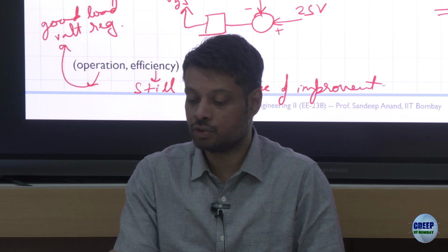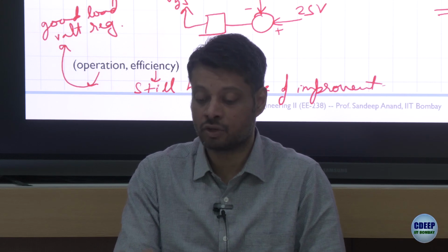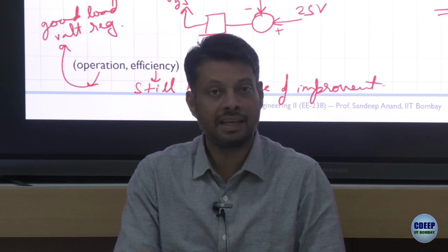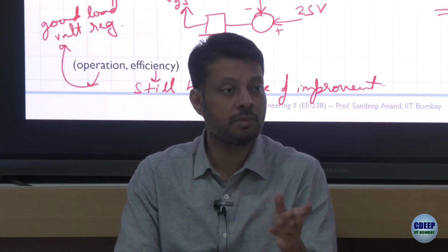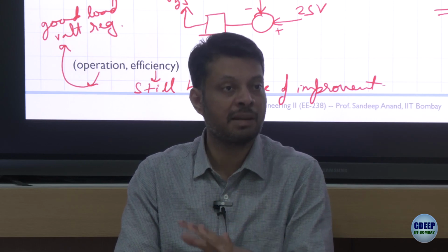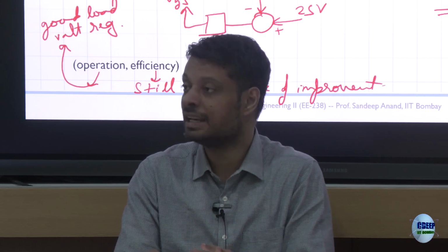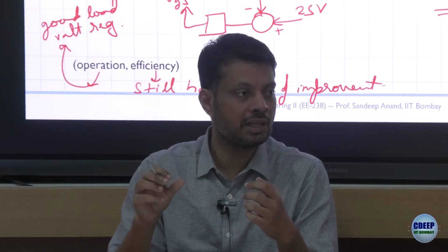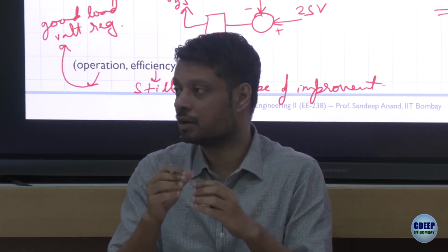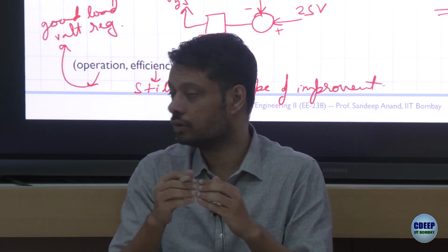If I suitably choose a channel current based on the load resistance, then I can maintain the voltage. So the problem of load voltage variation because of load resistance change can be taken care of by using a variable resistance, and of course some other circuit which can monitor the output voltage and do the subtraction, so we can figure out whether the output voltage is less or more, right?